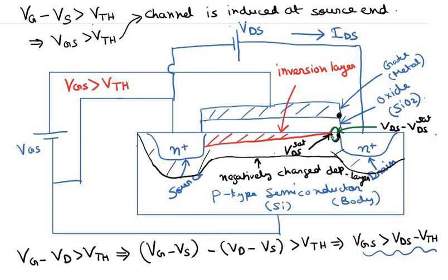This region transfers the electrons from the point at which the channel is pinched off to the drain, because there is a very high electric field. So this region does not have a conductance of its own, but only transports the electrons that the channel supplies from the left.